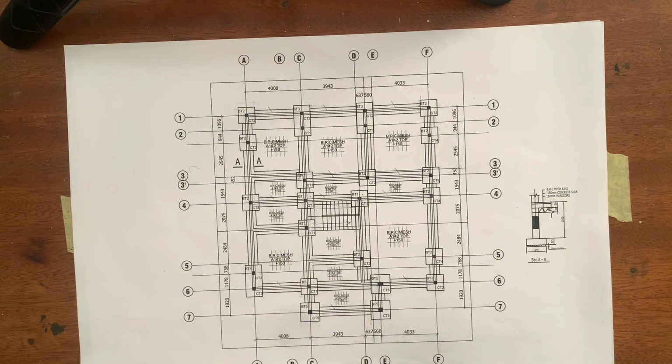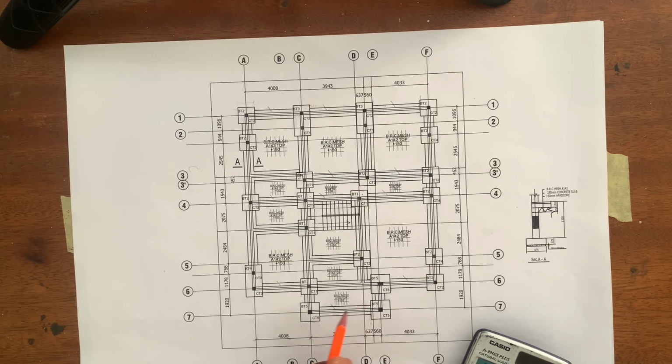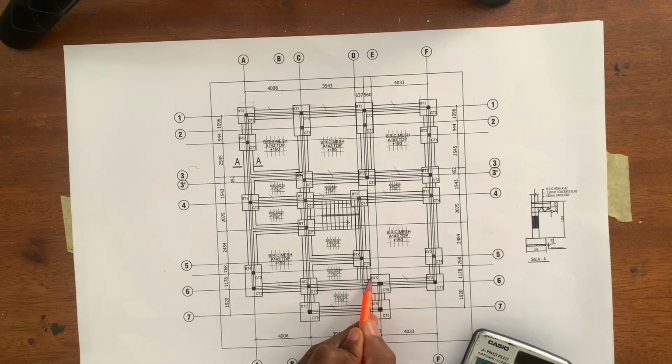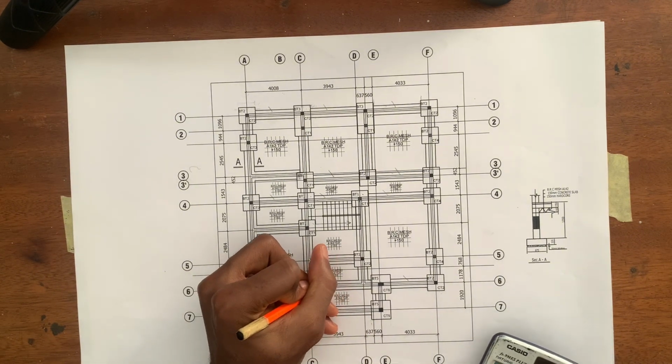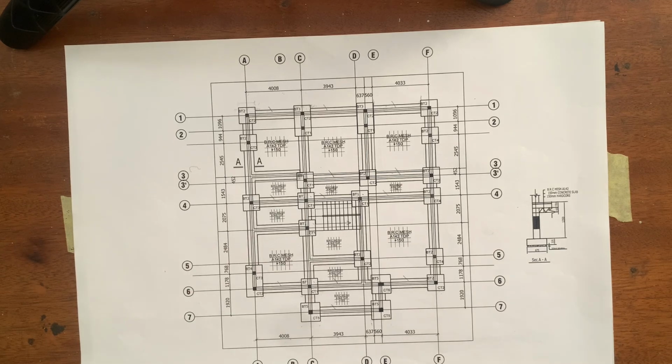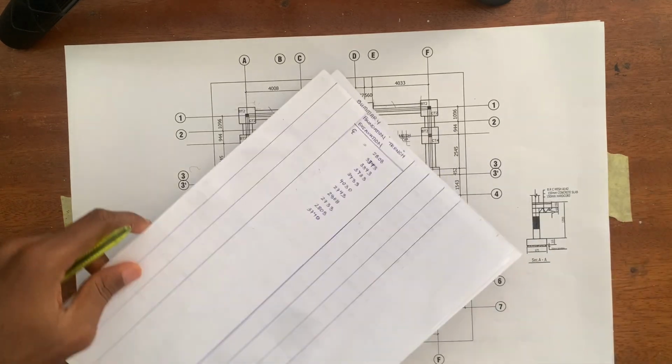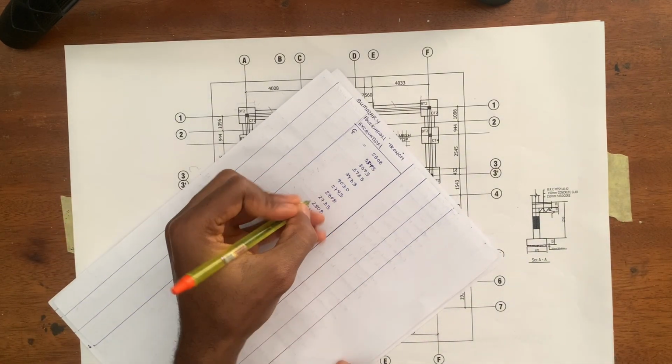So we're going to be minusing 600, and then we're going to be minusing half of the length of base type 5. So half of 1,400 will give me 700. So minus 700, so that will give us 3,840. So from here to this point is 3,840. So we've measured from this one. So what we need to do is record 3,840.